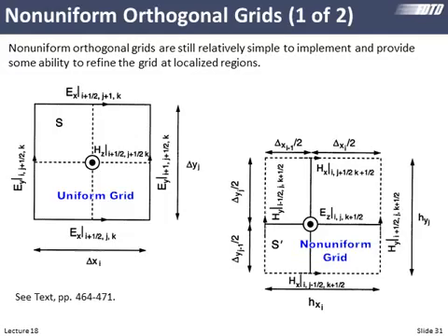This does not necessarily lower dispersion, but it does let us concentrate our computer resources where the field is varying most abruptly. If we didn't have a non-uniform grid, we would still always have to resolve the most rapidly varying field, but we'd be forced to have that fine resolution over the entire grid. So clearly that's not very efficient, and a non-uniform grid buys you quite a bit of efficiency with a little bit added complexity to your formulation and implementation.